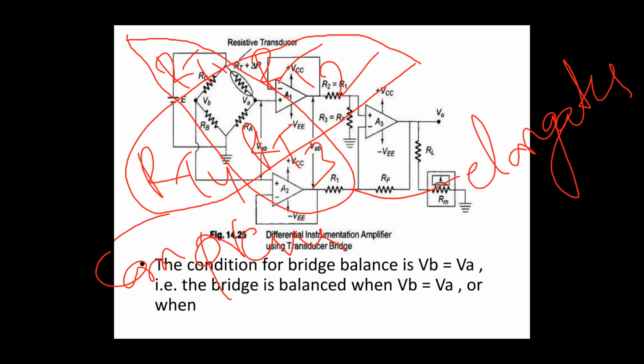The same circuit we are going to replace, with the resistors as strain gauges, mounted on a base in such a way that weight or external force is placed on it. One pair, RT1 and RT3, elongates, so their resistance increases.